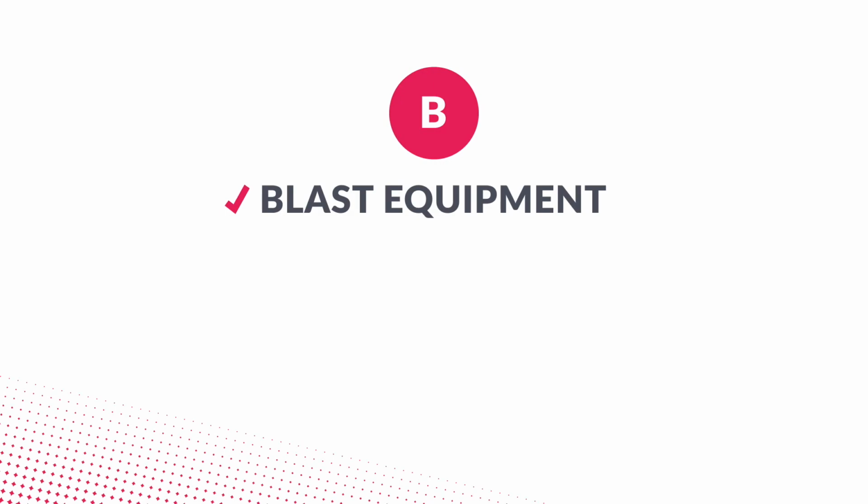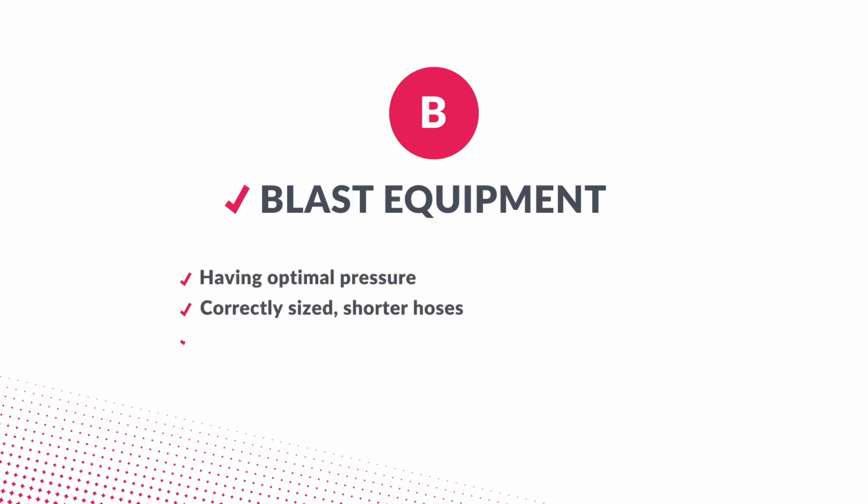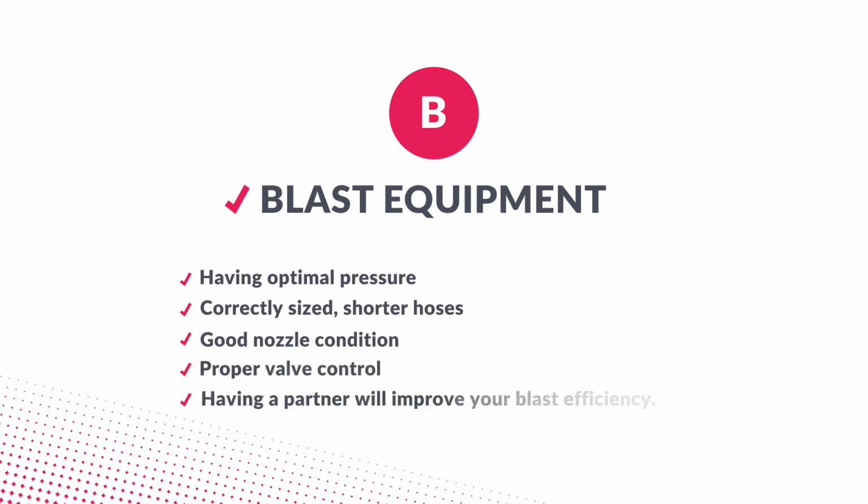In this video, we explained how blasting equipment can affect the overall efficiency of your blast operation. Having optimal pressure, correctly sized shorter hoses, good nozzle condition, proper valve control, and having a partner to adjust the abrasive metering will improve your blast efficiency.